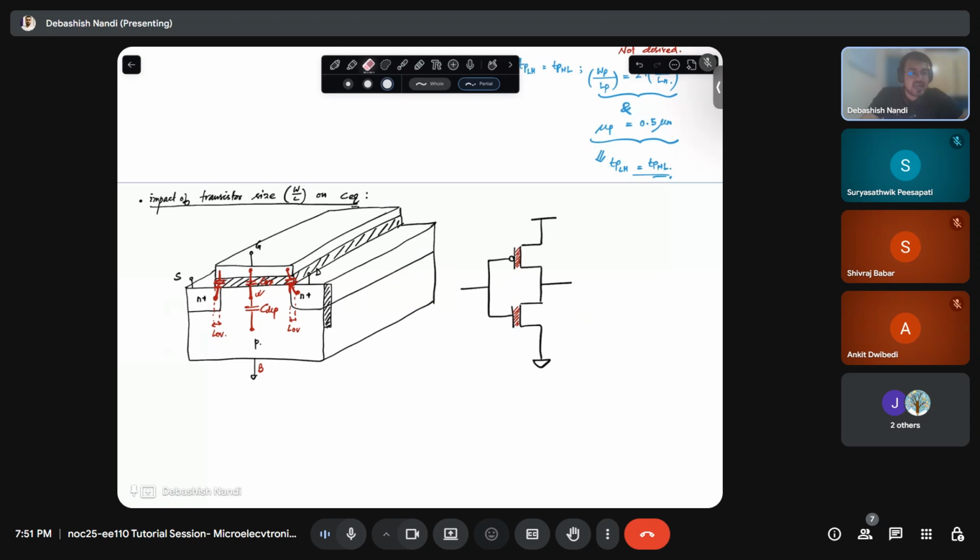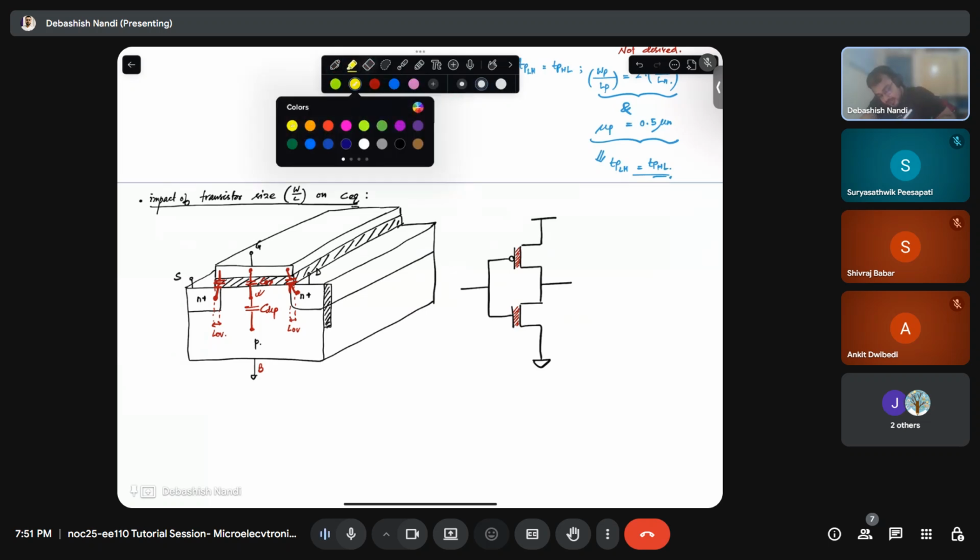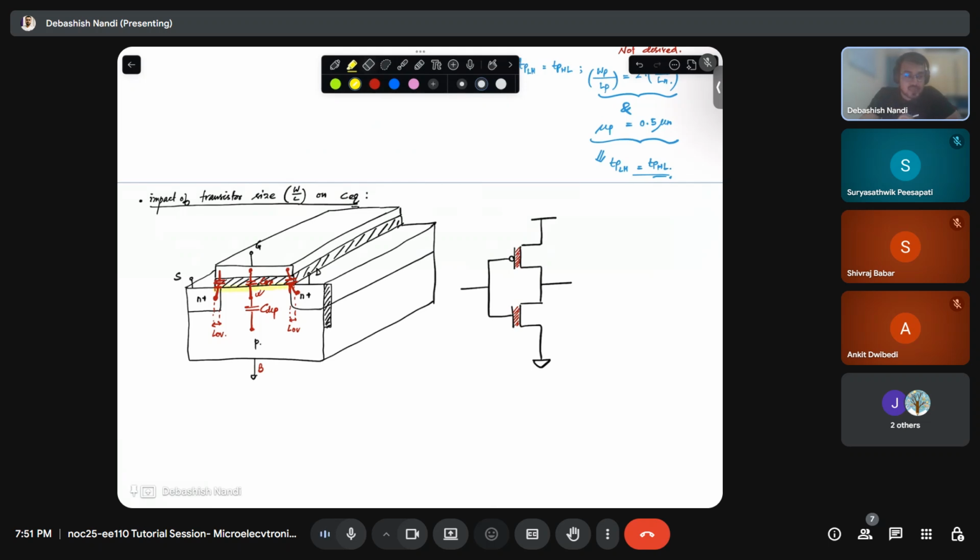So that silicon and silicon dioxide surface has to be a very clean surface, with as few impurities or impurity states as possible. The process to create this surface is very sophisticated compared to what you do in this region, because no transport is happening across this region. Transport is happening across the channel, at that position. So the material is the same but the processes are different.